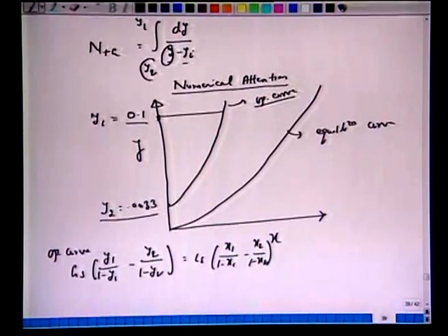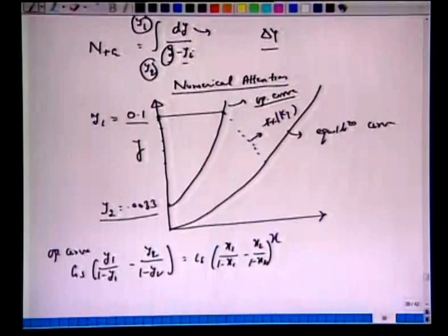So, we know the limit y2 and y1, dy over y minus yi. So, all we have to do is take several small units, right, del y. So, this is numerical integration, we have to work on del y. So, if you start from here, how do we get yi? Well, you have to take a slope of minus kx over ky. So, this was in the very first few lectures. We said that based on the driving force, we can obtain this yi here. So, this is the interfacial concentration. Given the bulk phase concentration, what is the interfacial concentration?